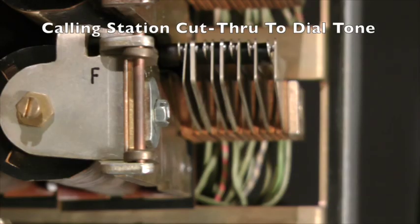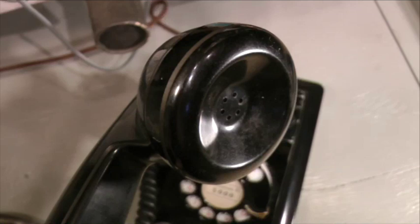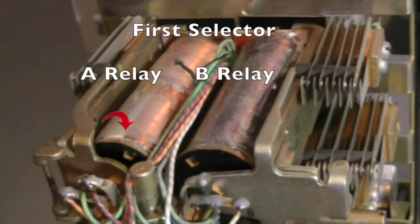The fully operated F relay holds the C relay operated momentarily to prevent further rotary stepping. It also closes the tip and ring transmission path between the calling station and the first selector. The first selector returns dial tone to the calling station. The loop through the calling telephone set operates the A relay in the first selector, which is quickly followed by the operation of the B relay.